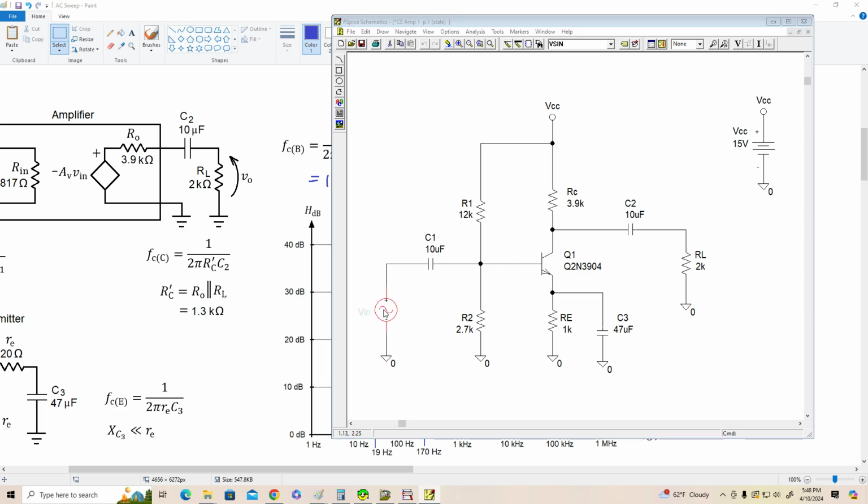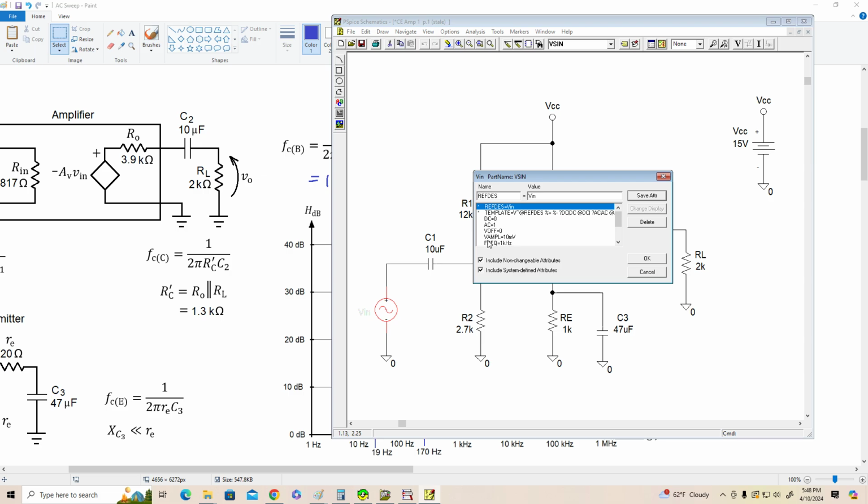And now what voltage are we sweeping? Well, obviously it's V in, but it's not the amplitude. We used 10 millivolts for that. That applies to the transient analysis. When we're doing an AC sweep, the AC voltage is the voltage that's applied to the amplifier. Now I set it to 1 volt, and normally that would saturate this amplifier like crazy.